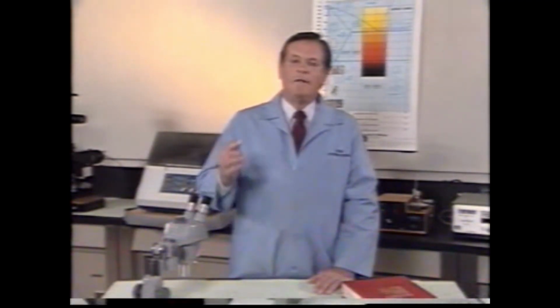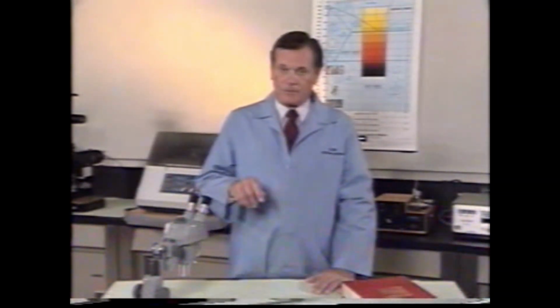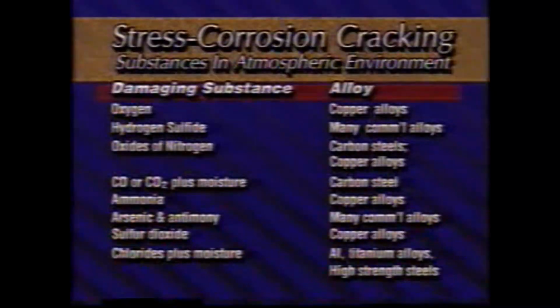Fractures caused by either of these mechanisms always initiate at the part's surface or at some location where the aggressive chemicals or environment can contact the metal. By corollary, if the crack is found to have a subsurface origin, corrosion fatigue and stress corrosion cracking can usually be eliminated as possible causes of failure.